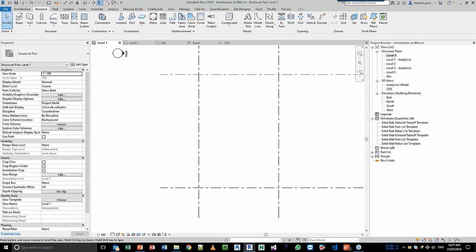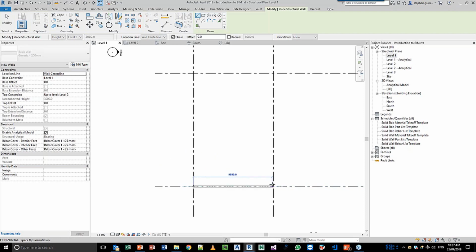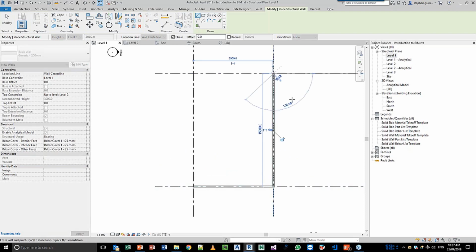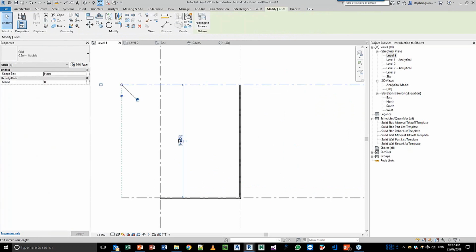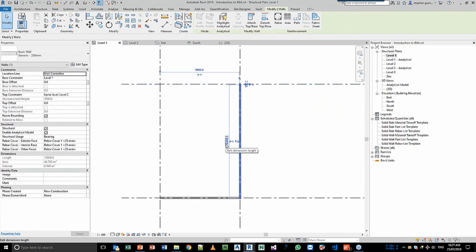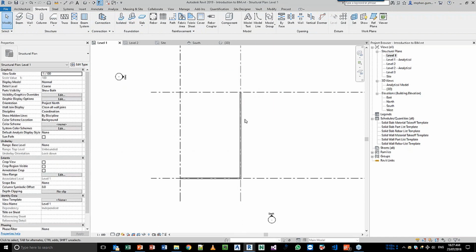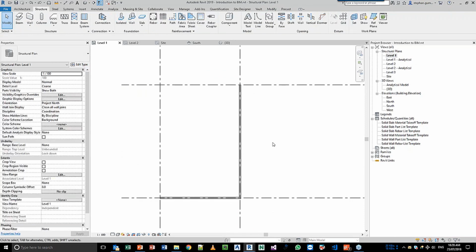If we go back to that wall definition again and talk about the fact that I can snap to these particular elements. So you can see I've snapped to the grids in this particular case. If I come in and maybe make this 15 meters, you can extend that out, and instead of being connected to here in this particular case, we may want to connect it to the next bit, and so on and so forth. So we can manipulate the bits and pieces as we go through.